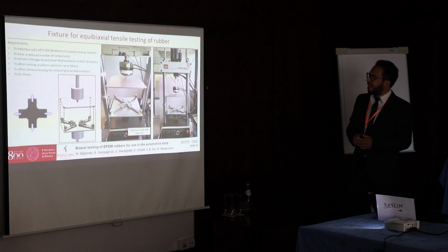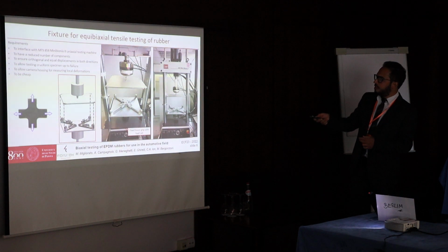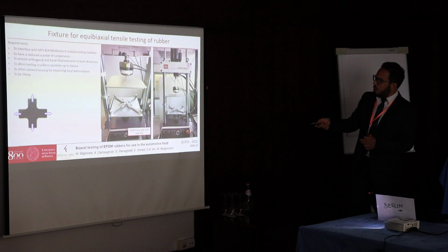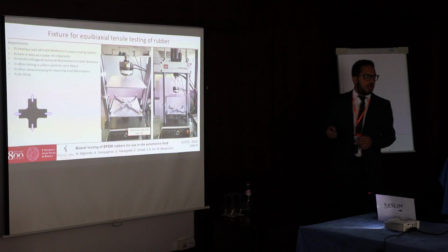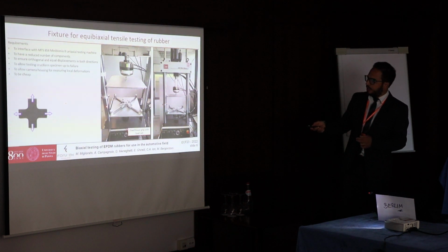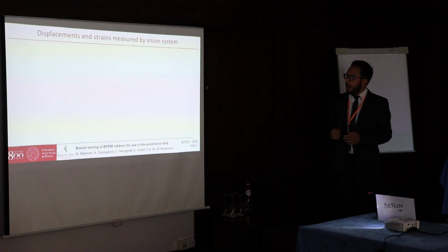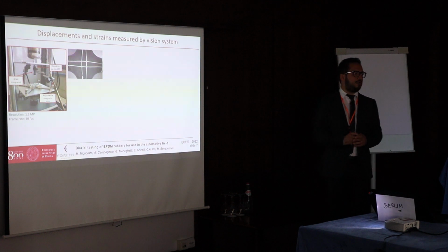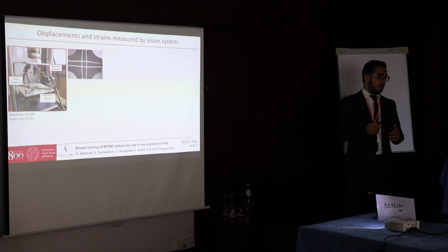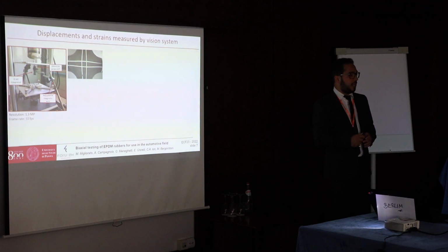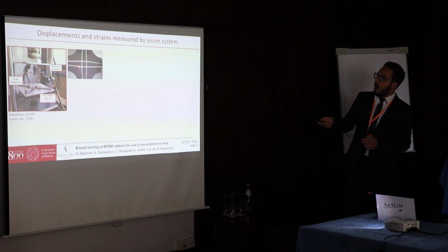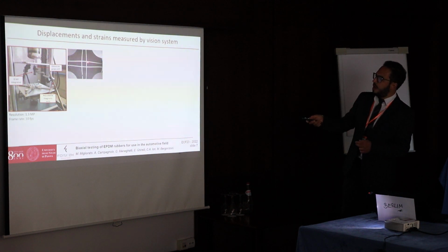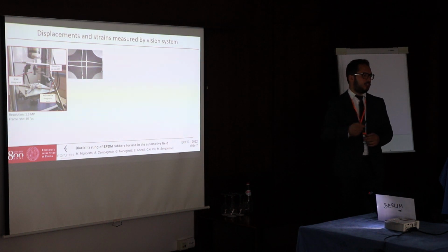Accordingly, we have developed a system which translates the vertical uniaxial displacement of a testing machine into two orthogonal horizontal displacements applied to a cruciform specimen using cables and pulleys. To measure strains in the central area of the specimen subjected to an equibiaxial tensile loading, a vision system has been developed. First of all, a white indelible marker has been adopted to trace lines and define a reference square on the surface of the sample.